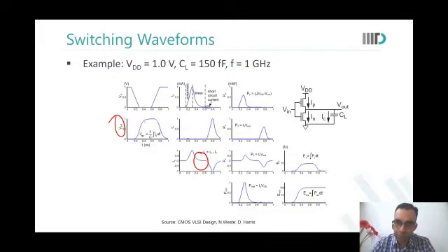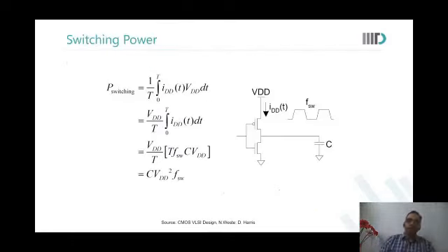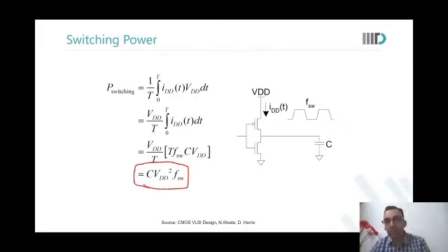Okay, that is 0. So what essentially we are saying is that the total switching power is C V squared times frequency. Why frequency? The number of times that the circuit switches, that many toggles will happen. 1/2 C V squared when the output rises, 1/2 C V squared when the output falls. So per cycle C V squared, multiplied by the number of times it would toggle in a second, so frequency.